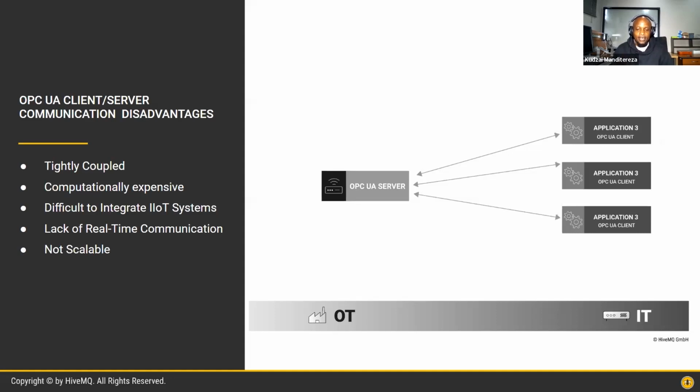So that includes things like deciding which protocols to use, what encoding to use, and what security mechanism to put in place. Now, due to the requirement of this sort of persistent underlying communication layer during OPC UA client-server interactions, it makes it difficult to use OPC UA in IoT devices that have limited memory and computing power for storing the connection information and for encoding the individual messages per established connection.